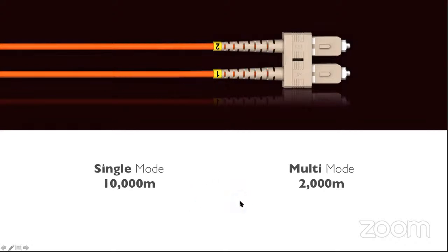Also, MADI is single mode or multi mode. So when you're dealing with MADI, you want to know, is your MADI network going to be single mode or multi mode? The single mode advantage, which is widely used in broadcasts, allows you to go greater distances versus multi mode. A lot of times, if the type of MADI is not expressed, I'm never a big fan of assuming, but if you had to assume, generally speaking, multi-mode is more the common standard, and then you have to verify that you have a single mode version if you want it.